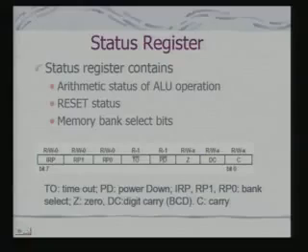If it is 0, then that data is stored in the W. If it is 1, it goes to one of the general purpose registers. Along with this register, there is a status register which plays a key role, just like a flag register, because a flag register stores the status of a computation. In this case, the status register plays that role, but along with arithmetic status, it stores other information as well.